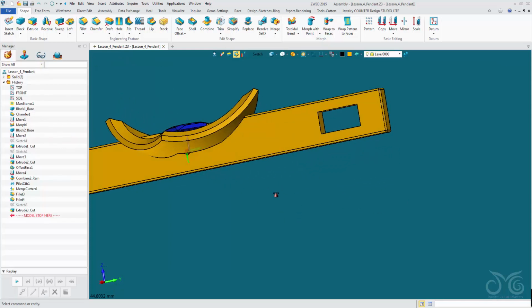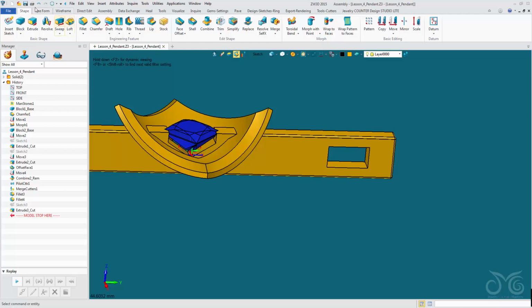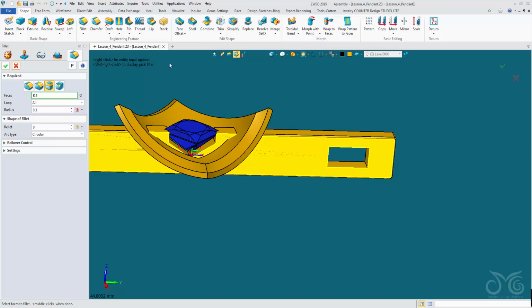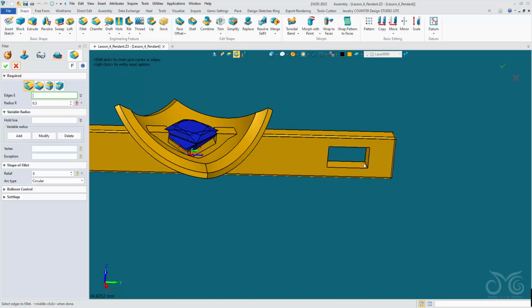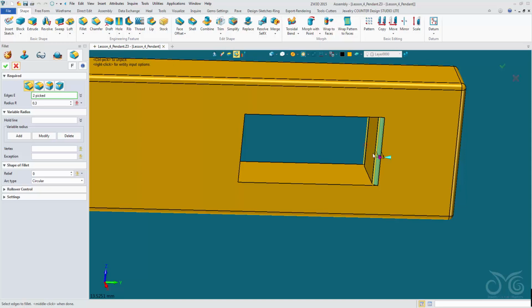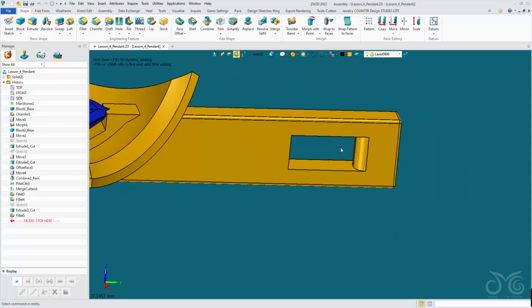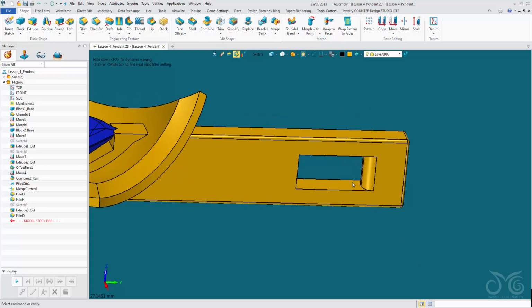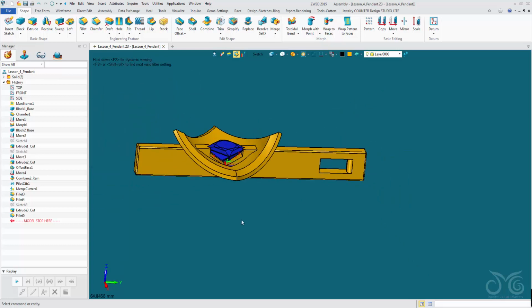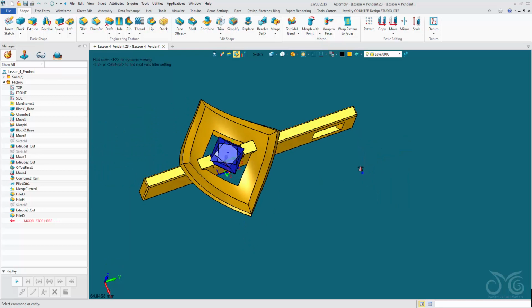Confirm the operation, and there we have our hole cut. Let's add in a final edge fillet, these two edges, drag it up. Let's give it a value of 1.25. We're just giving a nice fillet so that our chain will have a smooth edge on which it can rest. Okay, so this is essentially our pendant completed.